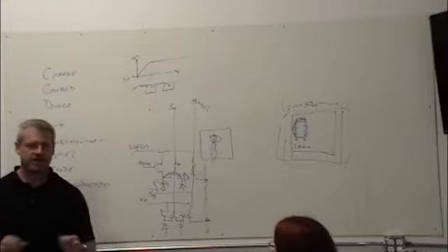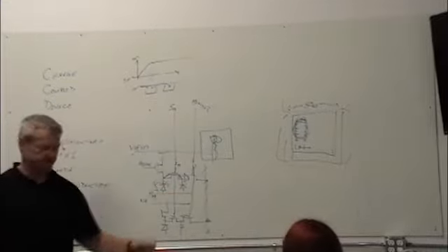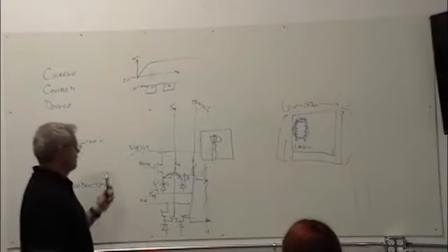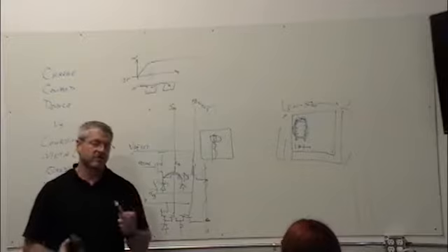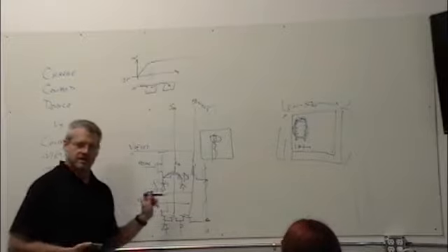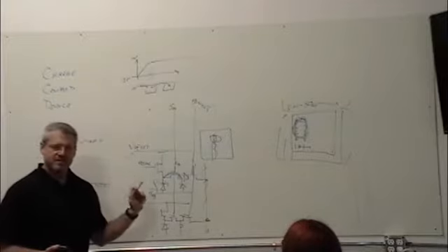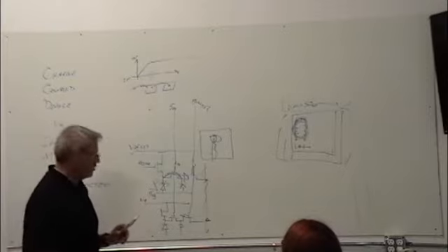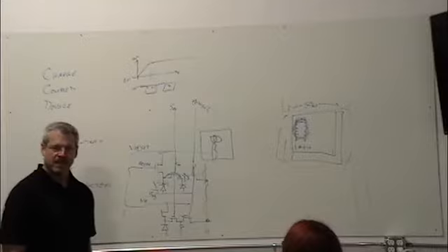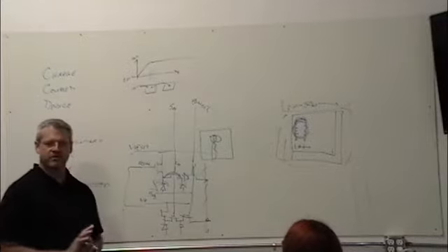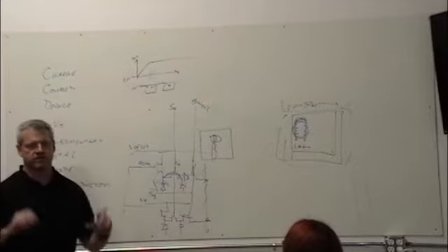I just emptied it all out and said, let's take a picture. Personally I covet them. It's called a global reset for a CMOS device. If it's a global reset, every one of these reset lines is tied together. And you can go boop, and reset it all at once and start your image. The whole frame starts at once.